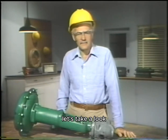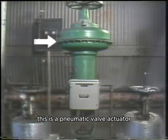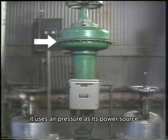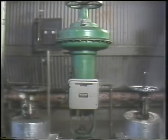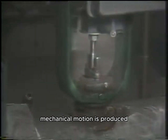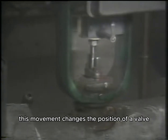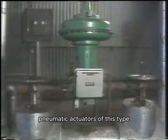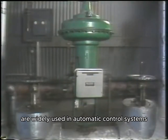Let's take a look. This is a pneumatic valve actuator. Like other pneumatic actuators, it uses air pressure as its power source. As the applied air pressure is increased or decreased, mechanical motion is produced. This movement changes the position of a valve, regulating process flow. Pneumatic actuators of this type are widely used in automatic control systems.